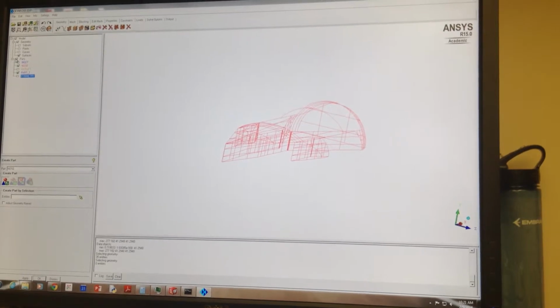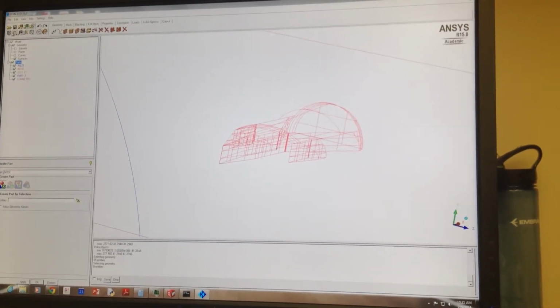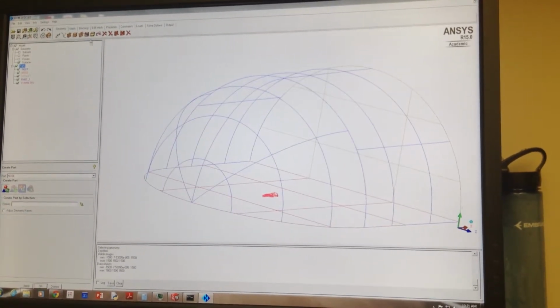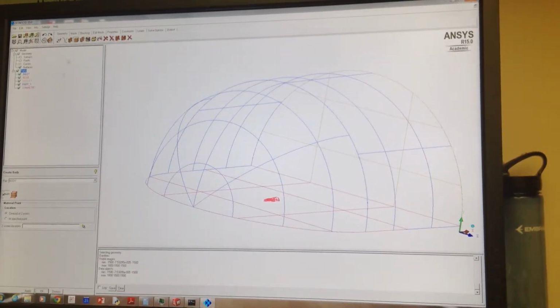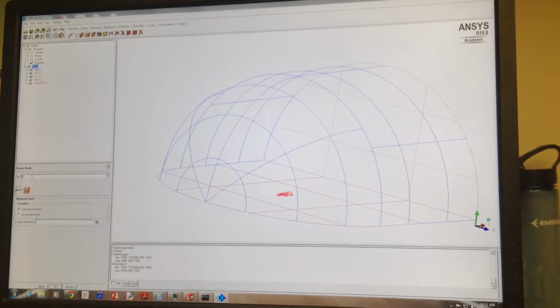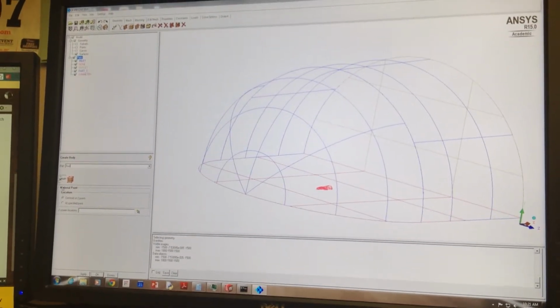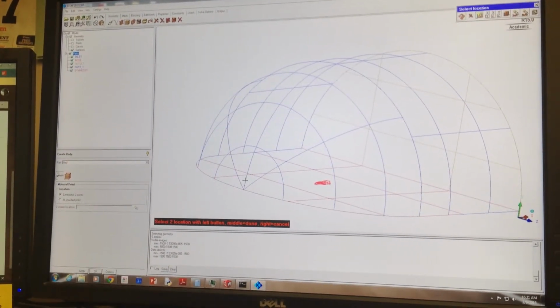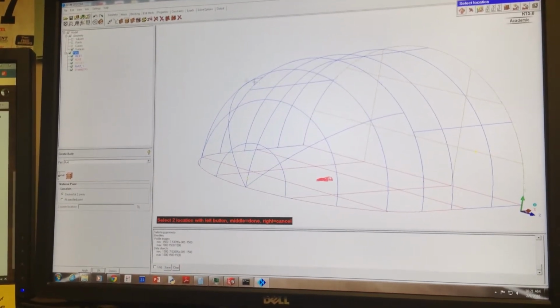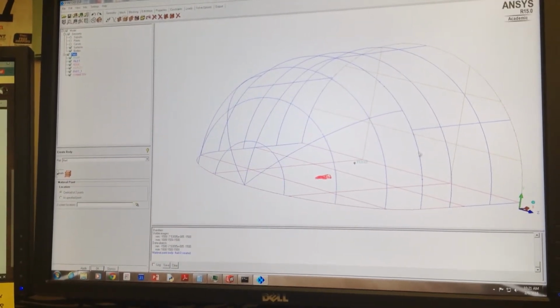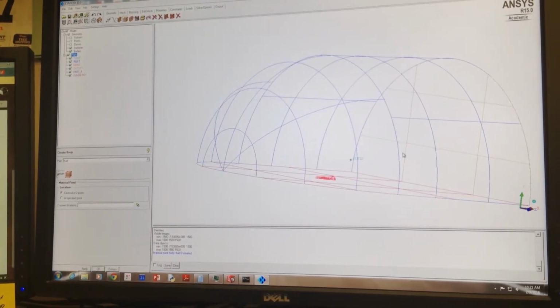I was going to ask, so we are done with name selections? Did you do parts for it? Now we have to create a fluid zone inside it. Go to geometry, go to this box, click over here, and just put fluid in here. Take 2 points, put in fixed. Any point on the domain, start and end. Then apply, middle wheel button.